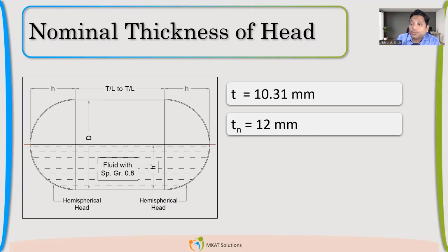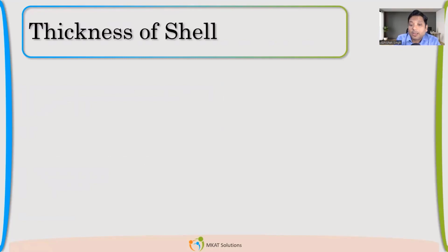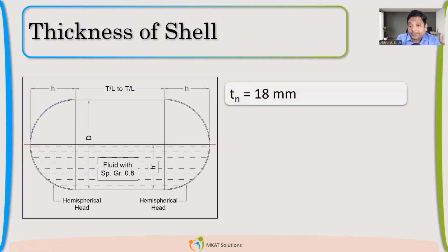So thinning will be very, very minimum. So definitely you can use 12 mm, because the forming depth is not coming into the picture. The forming is not that critical, so you won't get a lot of fiber elongation. So 12 mm I selected.